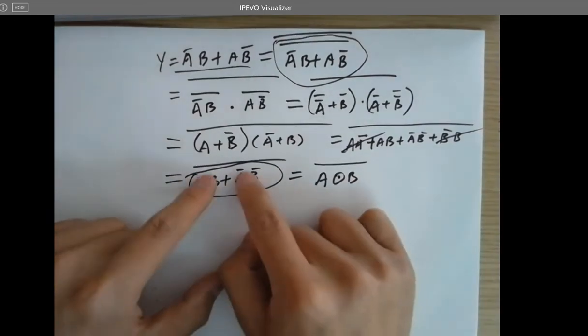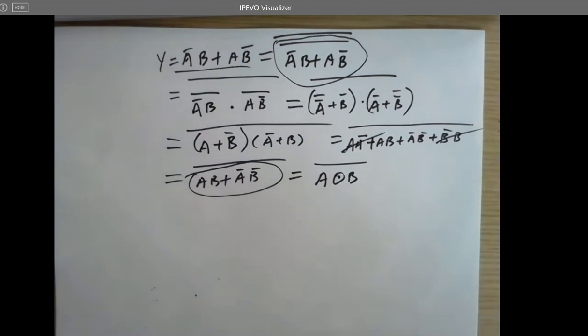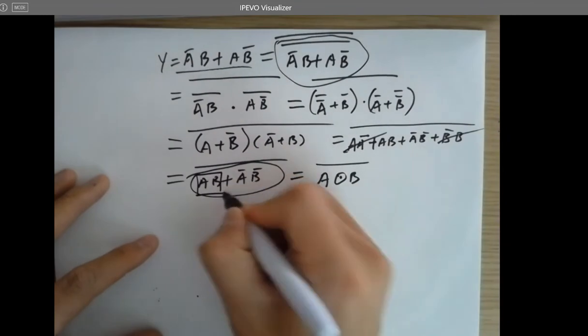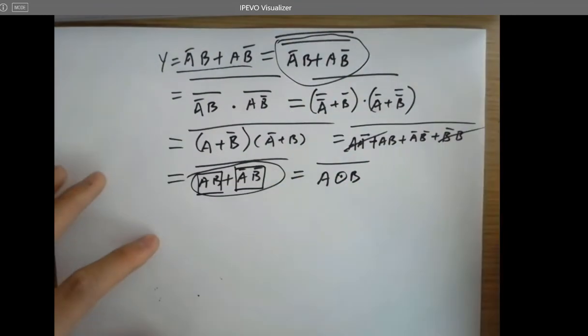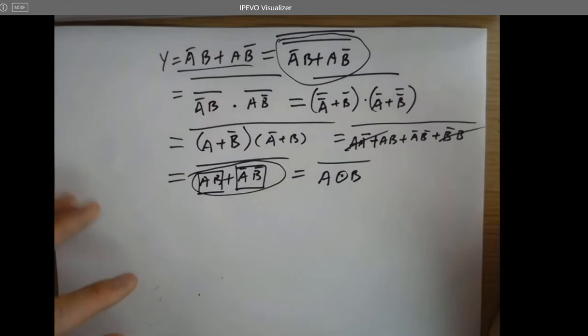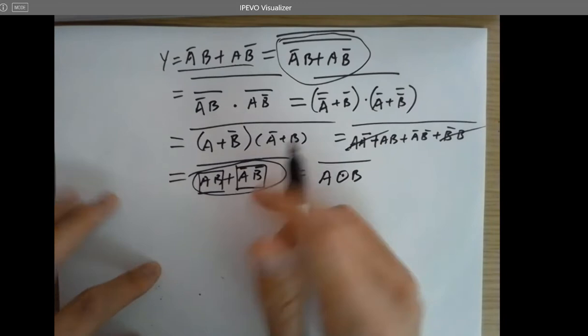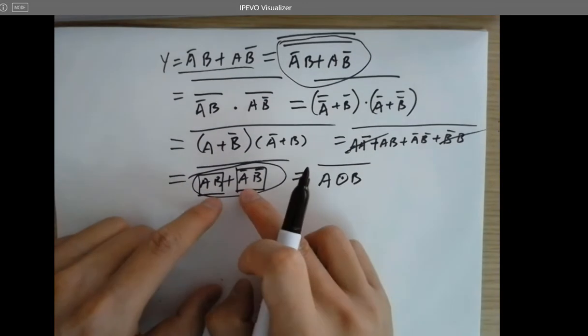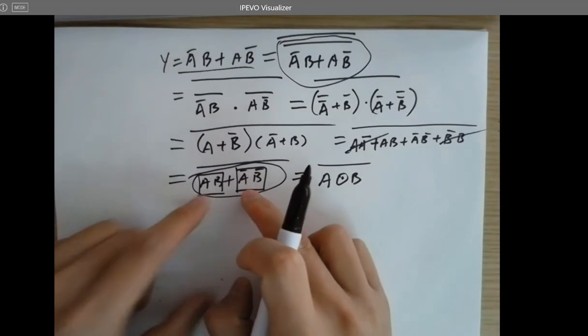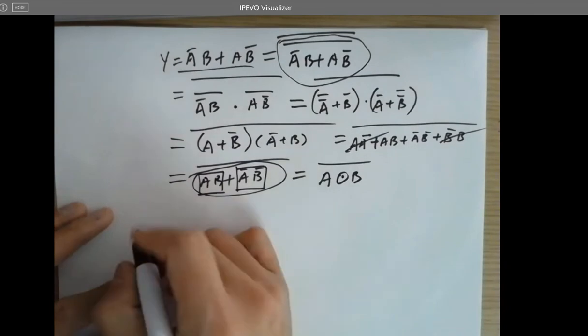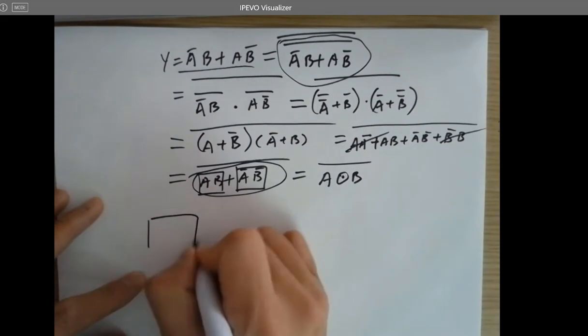So these two blocks need to be in series on the top for the PMOS and in parallel at the bottom for the NMOS. So let's assume these two logic expressions are two black boxes. You can imagine that this is a NOR logic, because OR then NOT, for these two black boxes.